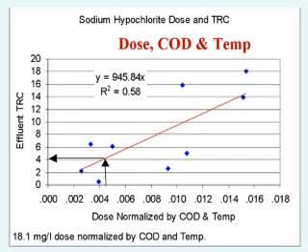So in this case, there's a family of curves here for different temperatures, and it's based upon that TSS data that says here's how we're going to dose our chlorine. At the beginning, you can have a very high dose. This is raw CSO used in Columbus that we're dosing. Could be from 40 to 60 milligrams per liter at the very beginning, but it tails off real quickly to levels well below 10, typically below 5 in a dosing scheme.